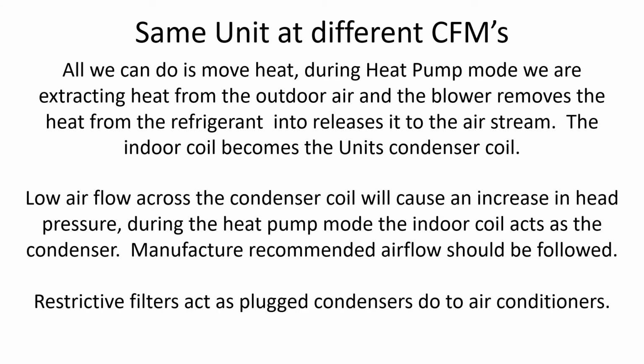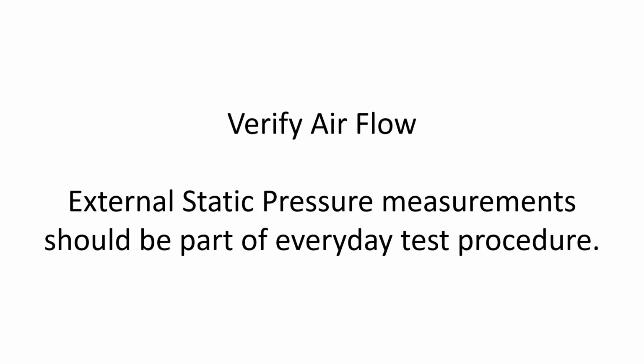Low airflow across the condensing coil will cause an increase in head pressure. During the heat pump mode, the indoor coil acts as the condenser. The manufacturer recommended airflow should be followed. Restrictive filters act as plugged condenser coils, just as in an air conditioner. Verify airflow. External static pressure measurements should be part of every day test procedure.